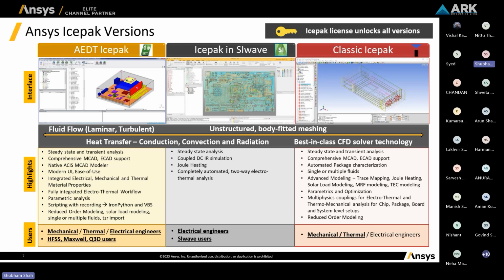You want to see the thermal performance if you use the same fan at 1 meter per second and compare it with 3 meters per second. So you can parameterize that inlet velocity condition, and you just have to enter the values: 1, 2, 3, 4 meters per second. That will automatically give you the behavior based upon which parameter you have selected.